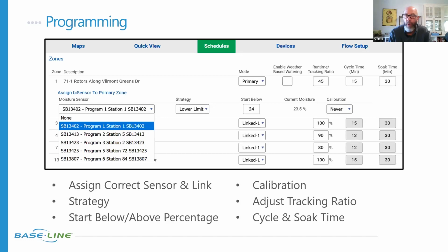But if you do it once, the behavior will be that if the system comes on and runs for the 45 minutes programmed into the zone and it doesn't find field capacity, then the next time the system comes on to operate, say you did your first attempt on Tuesday, then on Thursday, if it's scheduled to run again, it's going to run for 45 minutes plus 20%.